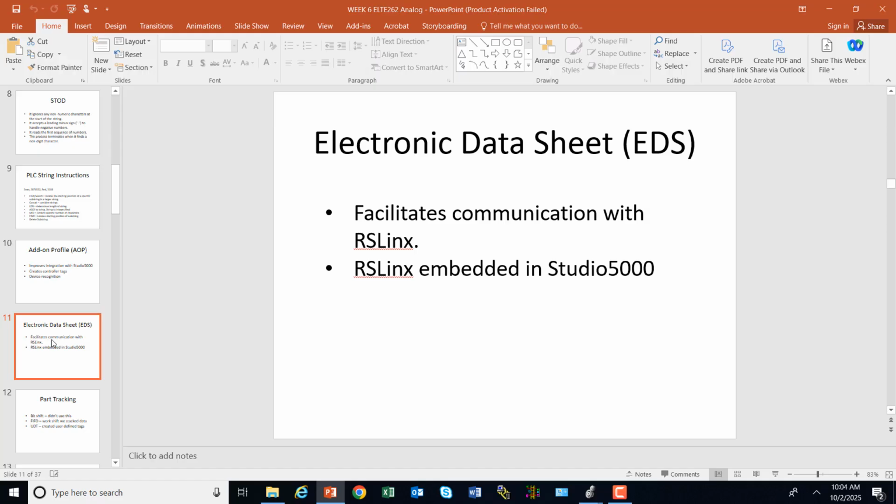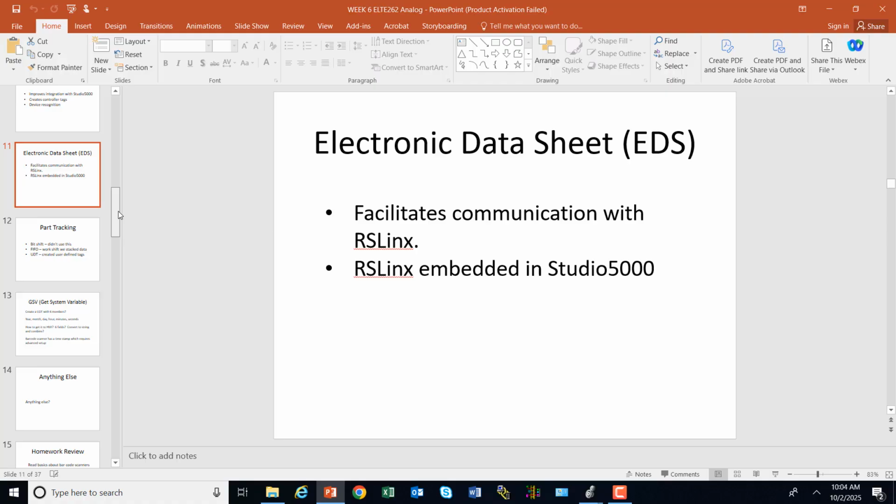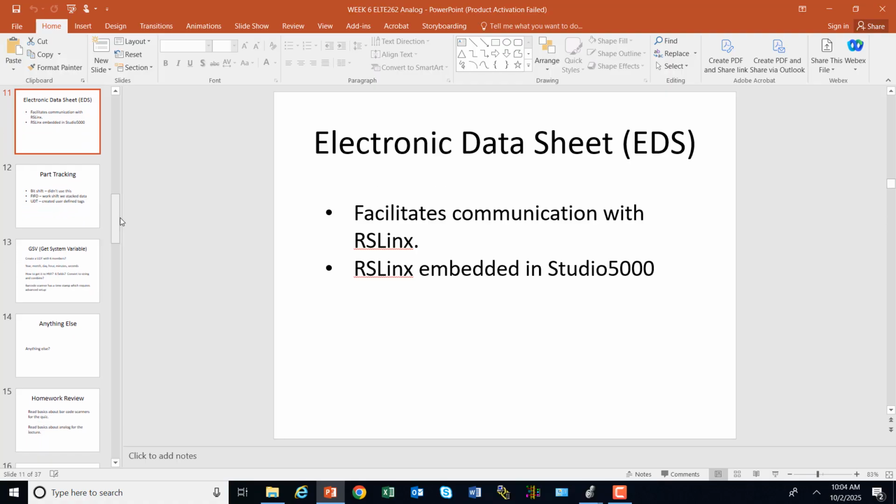What was interesting then, when we finally did load up the EDSs, it just went away. We couldn't even find it at all. And once we scanned that barcode to enable Ethernet I/O, then bang, it popped right back up. So once again, great little learning activities about the ups and downs of Allen Bradley software, hardware, programming, initializing equipment, everything like that.